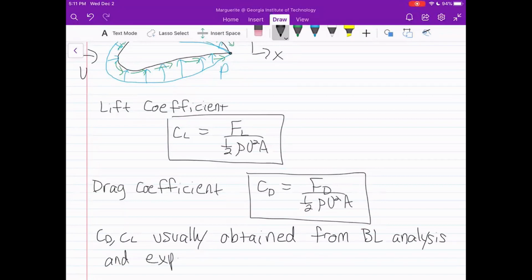So as you'll see throughout this lecture, there's this kind of stuff. You end up going and looking in tables and finding these coefficients depending on whatever kind of body you have, what the situation of your flow is, and then using that to calculate the drag force or the lift force, or maybe the velocity or whatever it is you're looking for.